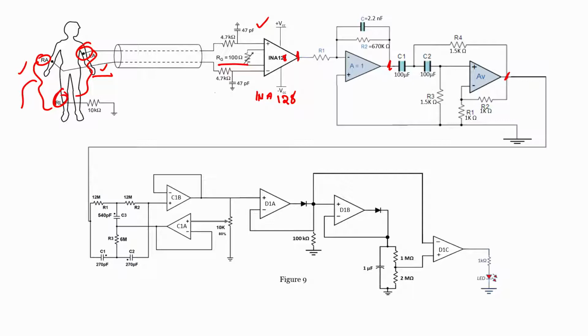But if you recall the discussion, initially we discussed, as well as the professor discussed in the class, that the raw ECG signal is always prone to a lot of interference and noise from other signals. Those are nothing but our power line interference, baseline wandering, and motion artifacts, all of which will be observed at this point. So we will try to see the effect of the baseline wandering in the system.